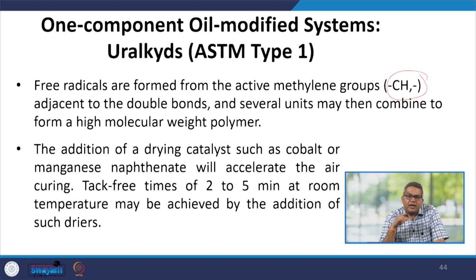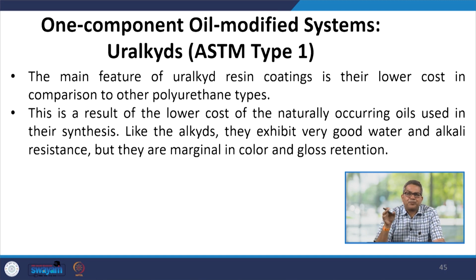The addition of drying catalysts such as cobalt or manganese naphthenate will then accelerate the air curing and reduce the tack free time to 2 to 5 minutes at room temperature. This may be achieved by the addition of such dryers.